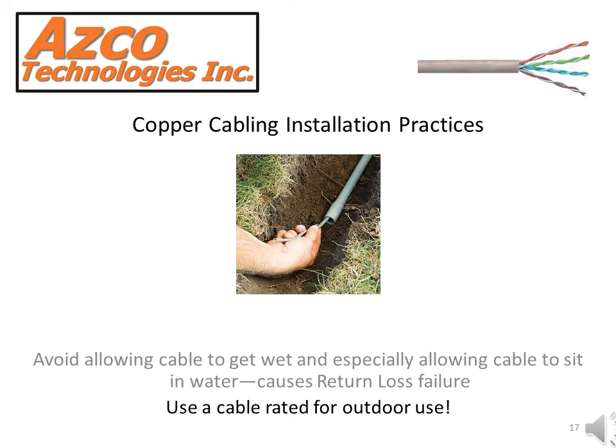Avoid allowing cables to get wet, and especially allowing the cables to sit in water. This can cause return loss failure or noise. Use cables that are rated for outdoor use. Often they are gel-filled cable, special for that application. Often we don't think that conduits under buildings will be filled with water, but quite often they are. So keep this in mind.